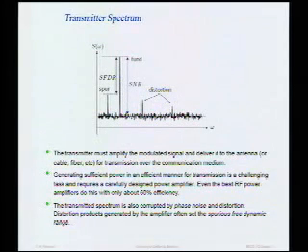Well, as we'll learn in this class, distortion is not only generated at harmonic frequencies, but intermodulation and cross-modulation distortion is also created at our own frequency. So if the PA is very nonlinear, it will generate distortion in band, which will actually corrupt the signal that you're transmitting. And we'll learn how that happens later on in the course.